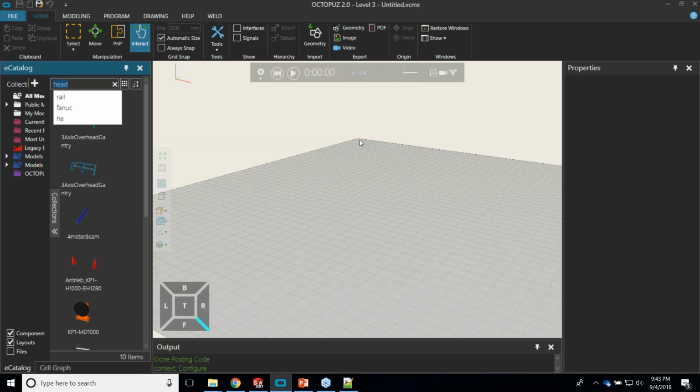So if you had 4 or 5 different tool paths come in from CAM, and one of those tool paths was a deburring path, and one of them was a polishing path, let's say, and they're using 2 different tools on the same housing, instead of doing a tool change, you would just change what the TCP was for tool path 1 and tool path 2. Maybe with an air move in between, but it would solve itself. That would be very straightforward.